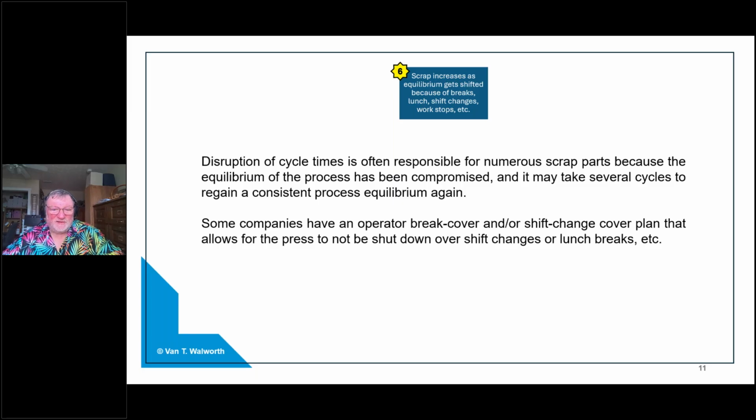Well, what happens is that after a few cycles doing that, the press will not have recovered enough heat during that slightly longer press open time. And as a result, something's cooling off. They're getting a non-cure. They're getting a mold fold. They're getting something that is happening that's not the normal things to happen. And so we need to compensate for the disruption in the equilibrium. It's one thing to consider, well, the press cycle got disrupted, but what you're really disrupting is the equilibrium that the press tries to have by running continuously and consistently.